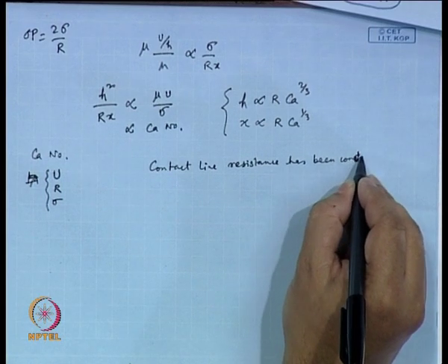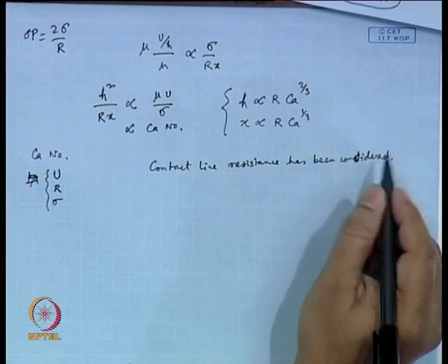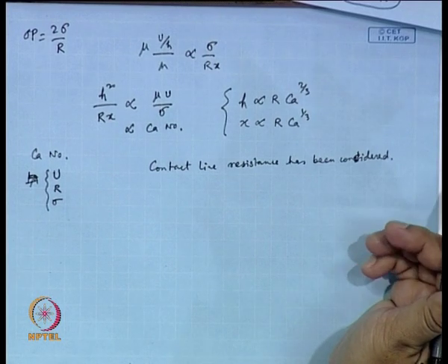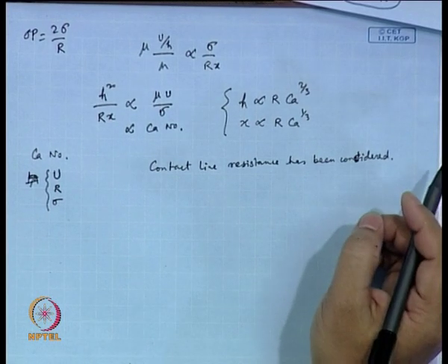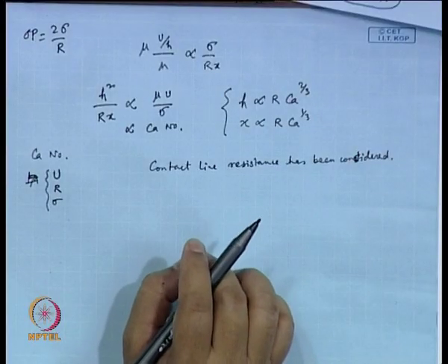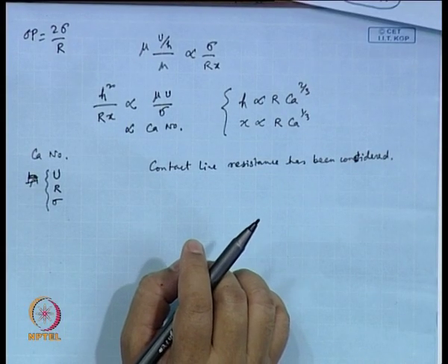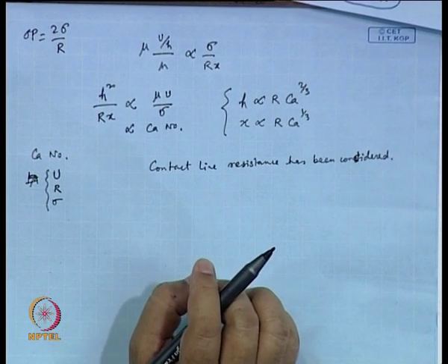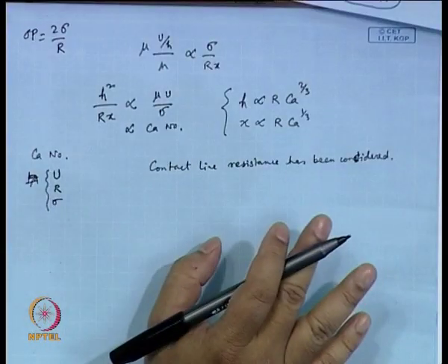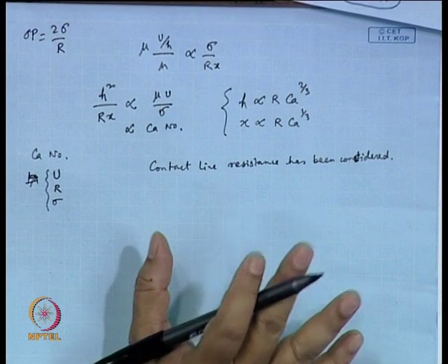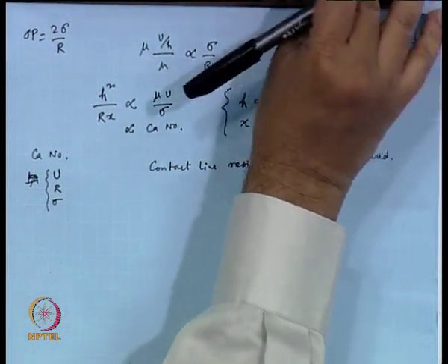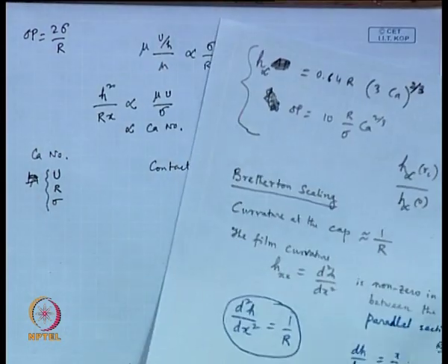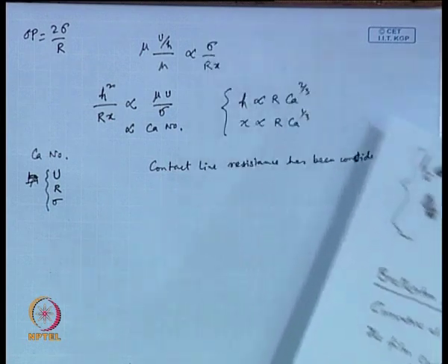Okay. But still, you have a pressure drop because of the two immiscible phases present in the channel, but it is not a contact line resistance. Okay, so that needs to be understood here. We are not talking about the contact angle or the hydrophobicity. We are not talking about contact line resistance. That is one assumption in this entire analysis, but still you have a pressure drop just because you have two immiscible phases flowing.